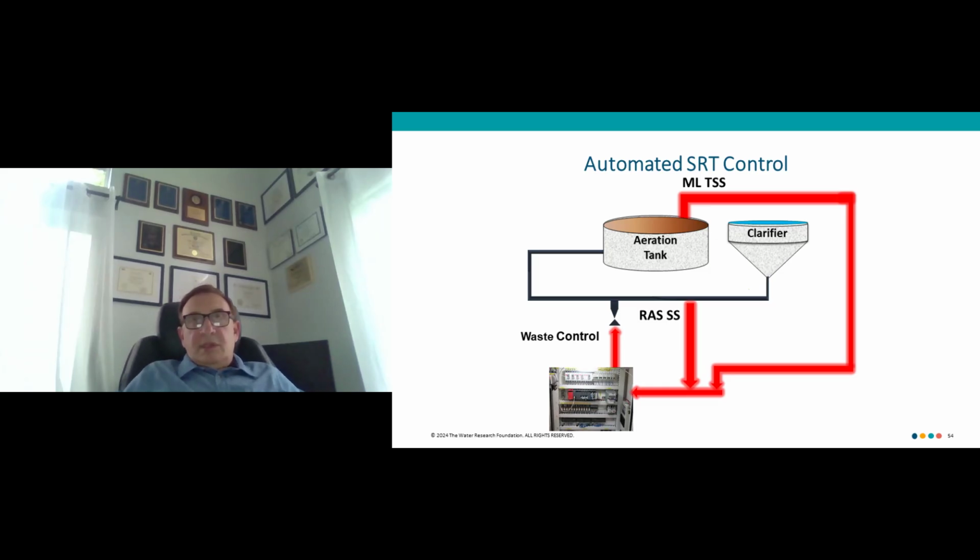As you know, ammonia removal depends not only on DO, but also on SRT, solids retention time. Precise SRT control is important for all activated sludge systems because it helps to maintain optimum food to mass ratio, the most important parameter of the activated sludge system. Especially it is important for low DO operating plants where optimum performance is required from both heterotrophic and autotrophic populations.